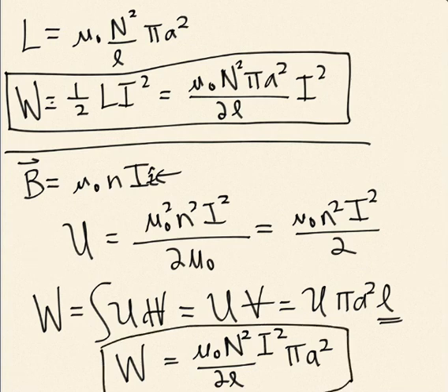And so at least for this particular case, I've demonstrated that you can think about the energy, again, fighting against the back EMF is how you spend energy to push the current through the coil. But we can see that if I believe that the energy density of the magnetic field is B squared over 2 mu naught, that's consistent with the fact that the energy is stored in the magnetic field. So the idea is that you've put energy into the magnetic field, which I can get back later. As if I discharge the coil, in other words, if I lower the current in the coil, there's going to be a back EMF that will prevent that current from lowering, and that will try to keep the current going.